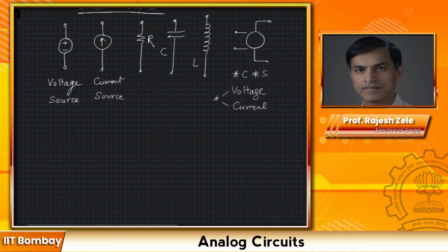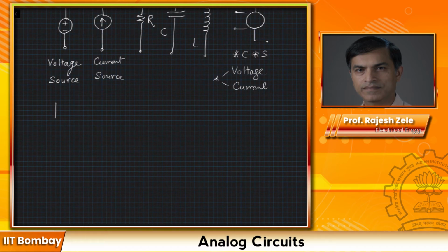Apart from these, we will be using devices. Let's start with the really fundamental. This is a diode. Now just so that you remember how to read this particular device, if you look at this device from here, you will see a K, and hence you can say that this is a cathode, which is a negative terminal. If you look at it from here, it will look like an A triangle. So we call that anode or positive terminal, and when you apply positive voltage to the anode, then the current will flow in the direction of the arrow, which is indicated by this triangle. If you try to apply positive potential on this side, then the diode will not conduct. So it acts like a valve, one-way traffic.